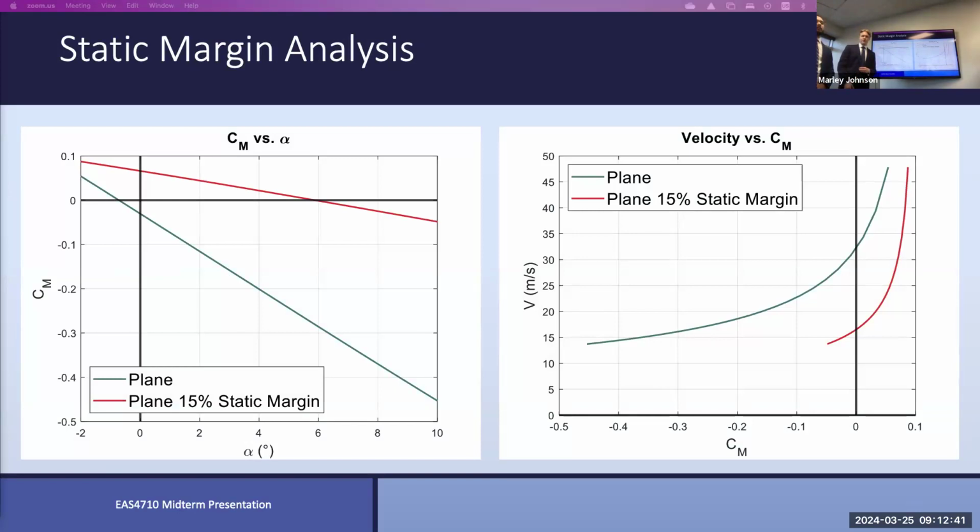You can get stability and eigenvalues, and visualize the stability motion. It gives you general parameters like coefficient of drag. So you enter your airfoil data, your weight, CG and stuff, and get results. And you said you did some MATLAB simulation.